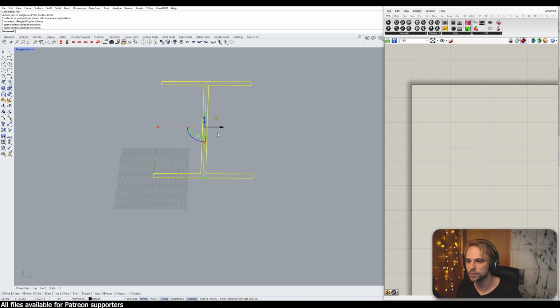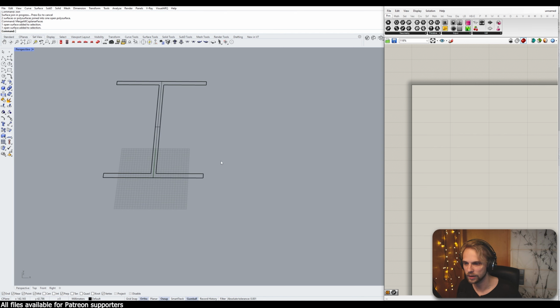So I'm just going to move it. Since this is 200 wide, I'm going to move it back by 100, because the origin point really matters in the blocks. I should mention this. Minus 100. So now 0, 0, 0 is placed right here.